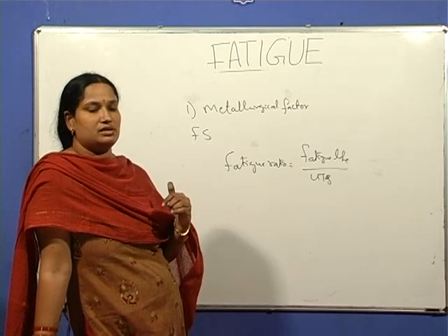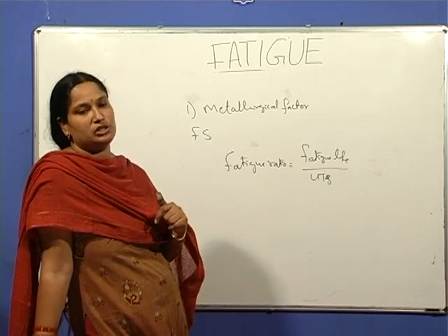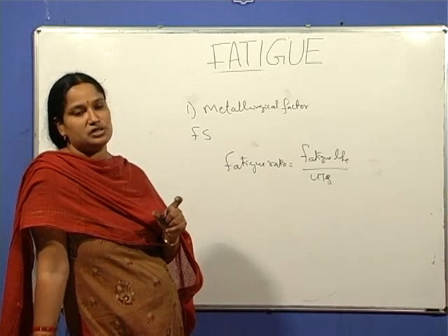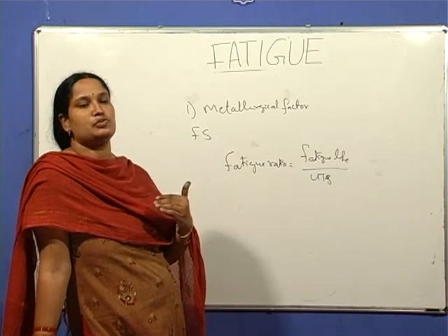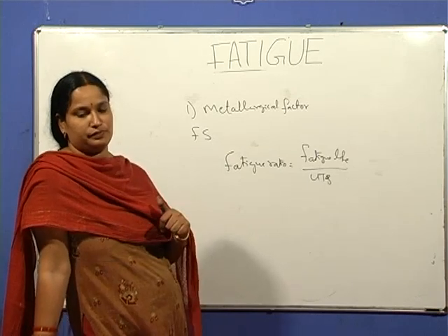So fatigue strength is proportional to the difficulty of dislocations to cross slip. The more difficult the cross slip, the higher the fatigue strength.